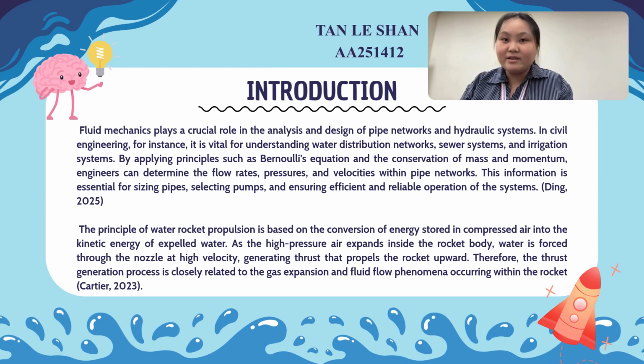Hi everyone, my topic is fluid mechanics in a water rocket launcher. A water rocket launcher is a practical application of fluid mechanics that uses compressed air and water to generate thrust. When the rocket is launched, the compressed air pushes water out through the nozzle at high velocity. This converts pressure energy into kinetic energy, producing thrust that propels the rocket up.